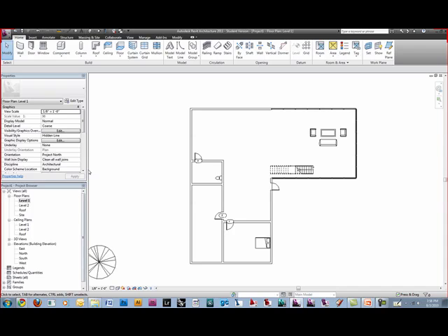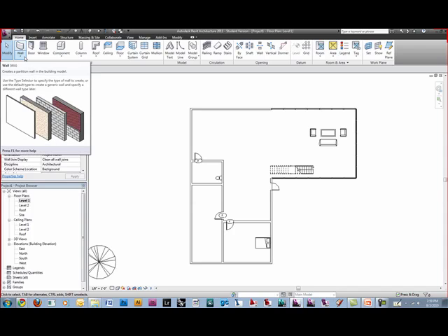And that's a trick that not many people use, and I'm not sure why they don't use it actually. And plus, those kind of lights don't have to have a ceiling, so if you just needed some light in the space, you just place those in without having to place a ceiling and do all that stuff. Because a lot of times your floor or roof is your ceiling, you don't want to put a ceiling in, and the studio lights are kind of a quick fix to get rid of that, or do a floor light instead. But the next kind of thing is a wall-based family.